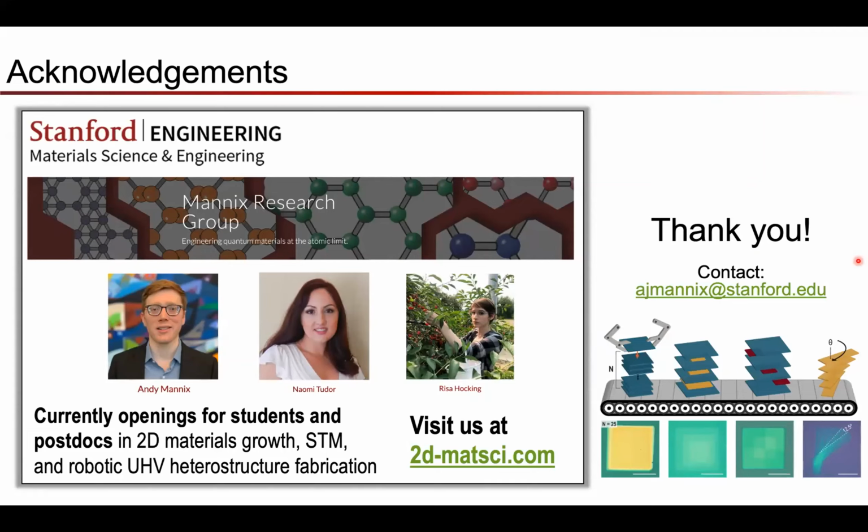So yeah, that's an excellent question, and that's something we've been very concerned about. To be honest, building the robot was actually quite easy. It was the optimization of the material quality by polymer engineering that took forever. We tried literally hundreds of different polymer combinations to arrive at the one we found to be optimal. And the tri-layer structure of polymers that we spin coat on top of our PDMS is key to reducing this problem that you mentioned.